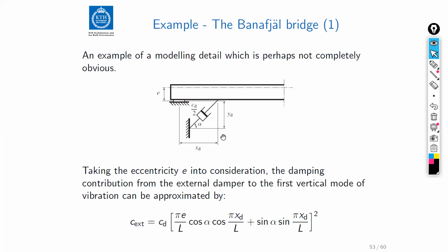This type of solution, of course, any viscous damper will need maintenance too, but at least in this case, we don't care about this tuning aspect. We only care about the damping aspect. So it's easier, and this image here comes from early preliminary analysis around this. What we've learned now is that in most cases you can actually mount the damper directly over the bearings here.